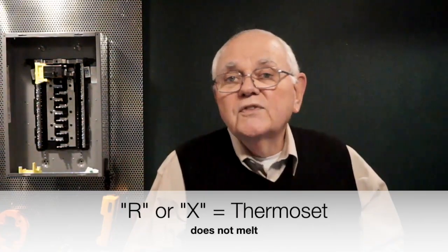One is a PVC insulation, which gives us our thermoplastic insulations. The other type is a cross-linked polyethylene, XLPE. Probably the most important type of insulation, one of the most common anyway, that we get from our XLPE insulation is our Thermoset wiring insulation. The Thermoset insulation is usually designated by an R, which R used to be for rubber, right? But we don't use too much rubber insulation anymore. We use a Thermoset insulation.